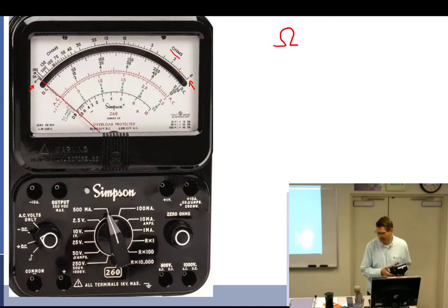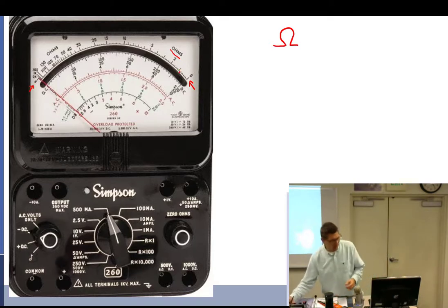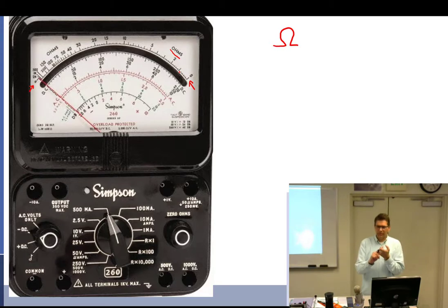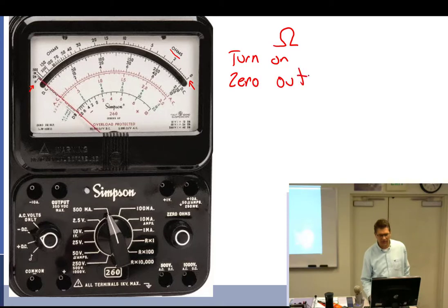All right. So always got to turn it on. You have to calibrate it. Turn on. 0 out. That's how I'll say that. 0 it out. And never measure ohms with battery attached.